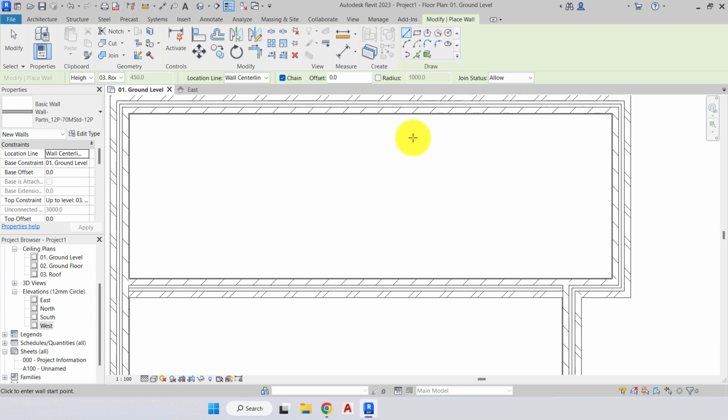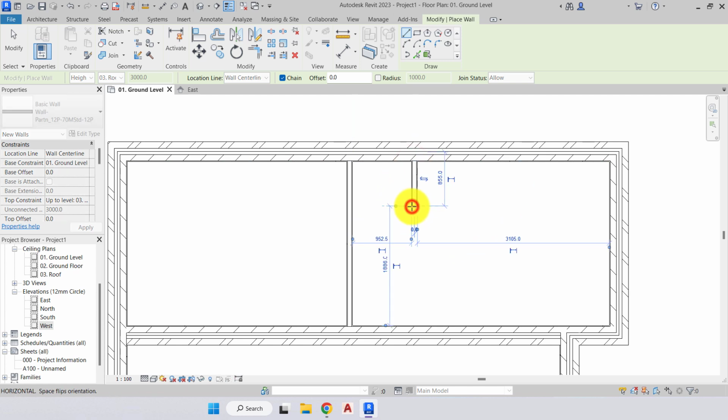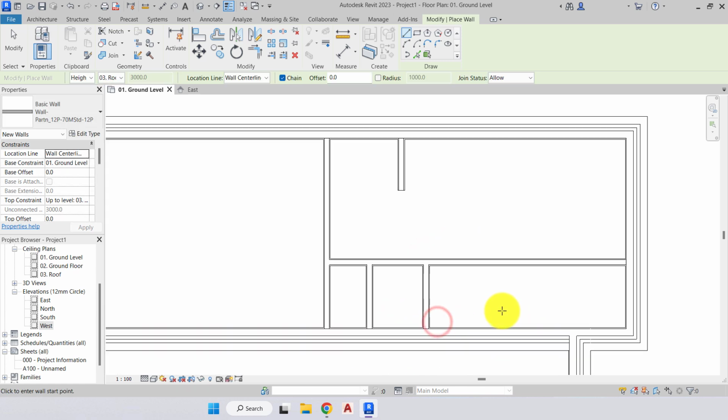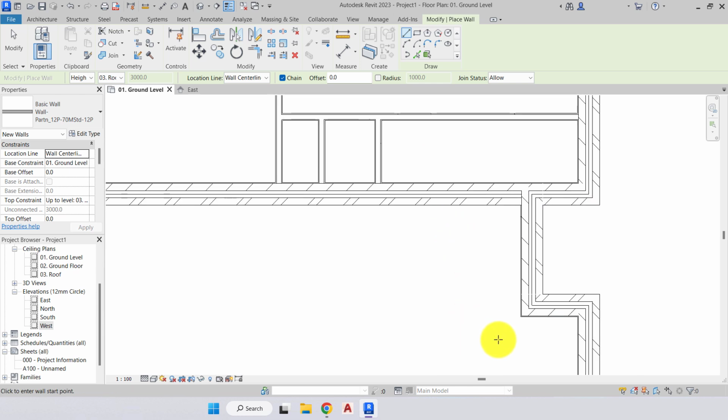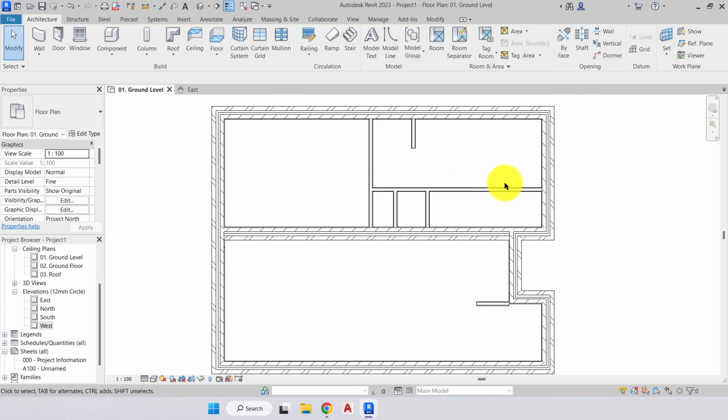So I'm going to zoom in to the top, attaching to the top wall, draw straight down, press escape, click on the top, click, press escape, attach to this wall on the left, over to the right, click escape, and then draw two walls inside that, click escape, and as well over on the bottom left, click and escape. So now we've just randomly placed in those walls.